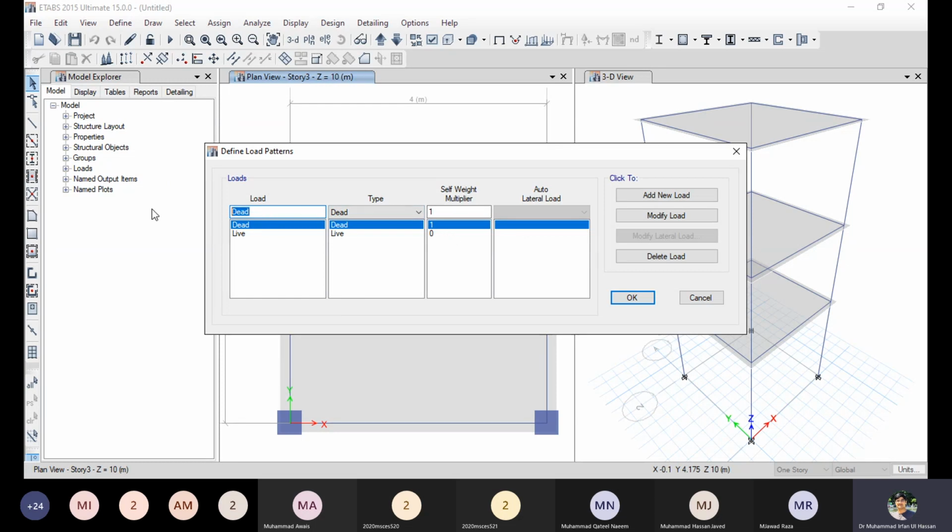You can apply some new load. If you only want to see the results of the time history separately, so I am writing here any kind of load. Let's say machine load or the seismic load, and I am applying here the periodic load. So let's say I'm saying it as TH, time history, periodic.